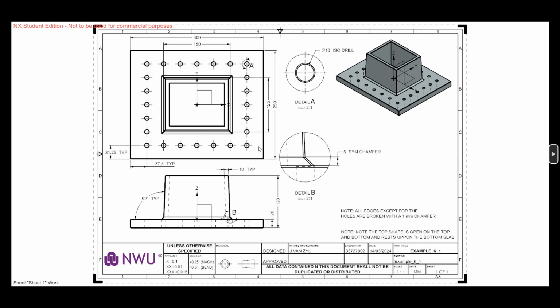And then before I say finish sketch, there's one more thing. We have these holes on this slab and we give a distance from the edge, and we also say over here from this detail view that it's a 10mm ISO drill hole. So you should use the hole feature or hole function, whatever you want to call it. So you need a point to reference from. So while we're on the sketch, we can add this reference for where to start.